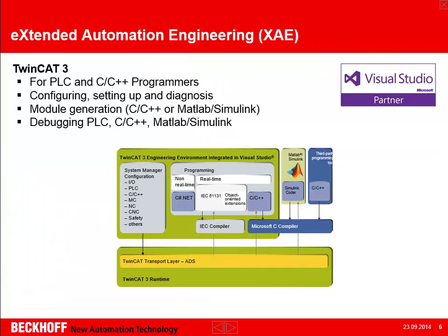Well, this is also an overview. So we integrate everything into Visual Studio on the left side here, with the system manager, with all the configuration of IOs and keeping everything together. But then we have the part of C# for non-real-time programming and execution, but also the programming environment for everything on IEC 61131, which is using an IEC compiler.